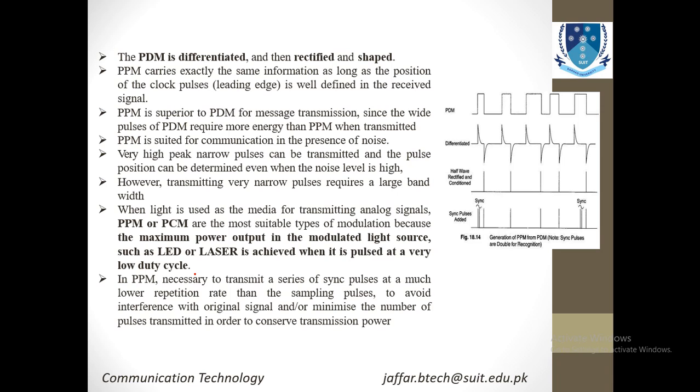So if you are reducing the time, because of the time position in the pulse duration modulation, you are in the frequency domain expanding the frequency. It means that the bandwidth requirement has been raised. So you have to keep in mind that your pulse should not be so narrow that you exceed your bandwidth threshold.